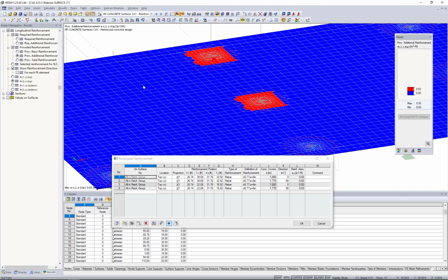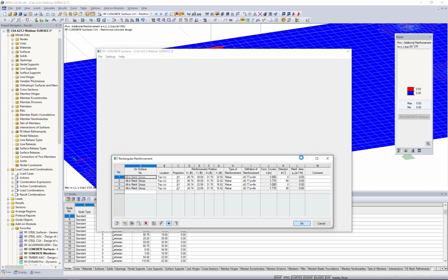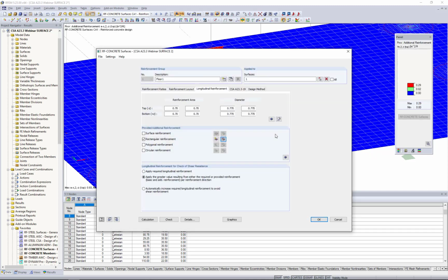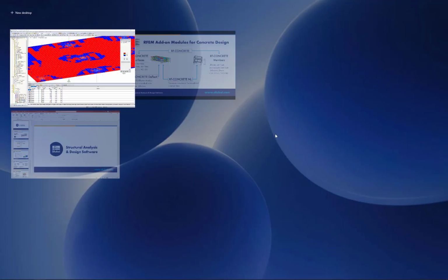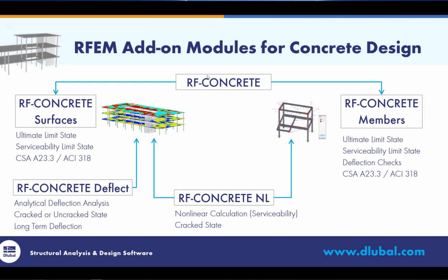Now maybe we'd want to do the same scenario for higher bending forces along the bottom of the slab here for a rectangular area spanning between the columns. So again, just a little bit more control over where you're placing that additional reinforcement rather than having the program determine that for you. So that's just something real quick that I wanted to show you, but of course we don't have time to expand on that much further today. So we'll go ahead and conclude our webinar today.